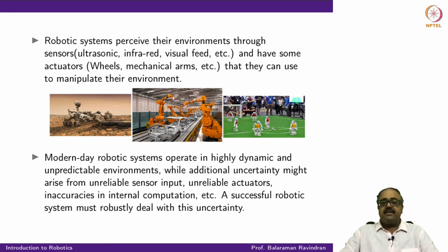It turned out that the gear assembly that we were using had very high quality plastic gears. And after several hours of operation, the plastic gear started wearing, and therefore the controller needed to be adjusted to account for that. And since we were not getting very accurate feedback, in fact we had no way of measuring the wear on the gear, and because we were not able to model that, even though we had a good controller, it kept failing every so often. We were able to redesign a controller based on the measurements that we could make, but then that again did not stay stable.